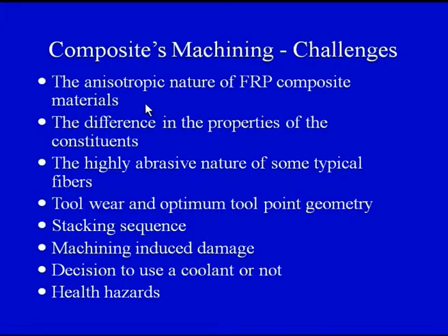But in certain cases, in order to have some specific design requirements, or in order to design a composite material for a specific application, we may have these layers of different materials also, such as, on your screen you can see the words stacking sequence. We can have different layers of different materials, which is called the change in the stacking sequence.